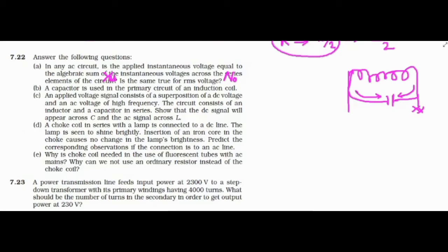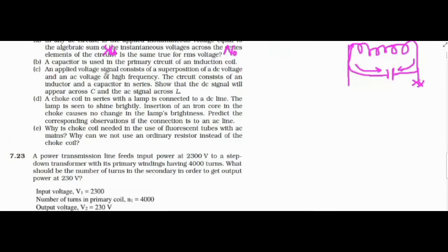Okay, so your answer could be like this. When we switch on or switch off the induction coil, a large back EMF is produced. As its magnitude is very large, it can produce the spark. If a capacitor is connected in the circuit, this large induced EMF is used to charge the capacitor, so that there is no problem of production of spark.